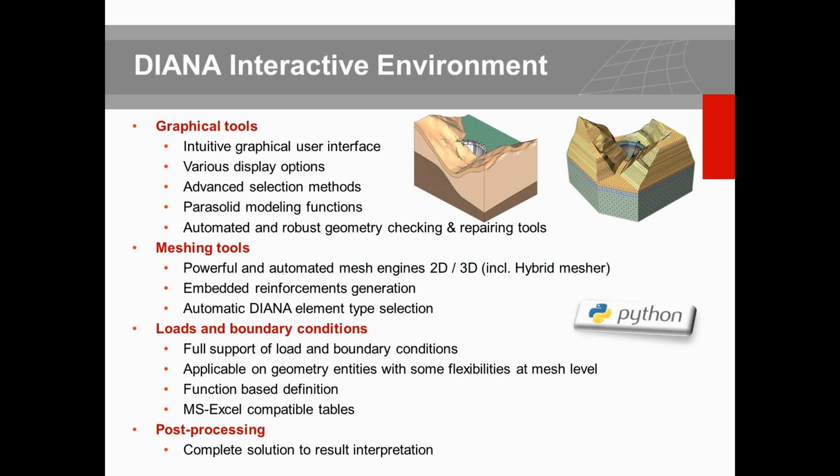And also we have enhanced the process of modeling reinforcement, embedded reinforcement or tendons or bars, and also creation of interfaces. For loads and boundary conditions, we are talking about the capability of various types of loads and boundary conditions being assigned based on different coordinate systems, including a manual one. A new definition and procedure has been introduced regarding the boundary elements for thermal or groundwater flow analysis.